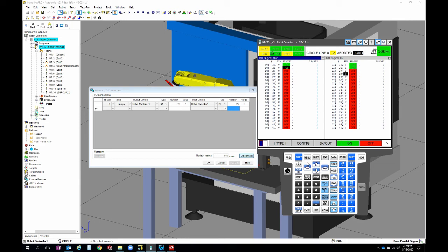Now if I go over, moment of truth, to my group input, now I've got a 3 there. I configured this group input to monitor these four digital inputs. So with these 2 on, that should have been 3, and that's what I'm seeing there. So just a way that we can cheat, I guess. Well, I'm sure that's how it's designed to work on RoboGuide, but a way that we can cheat it to make our digital inputs function like they would if they were receiving a sensory input from the environment somewhere in the real world.